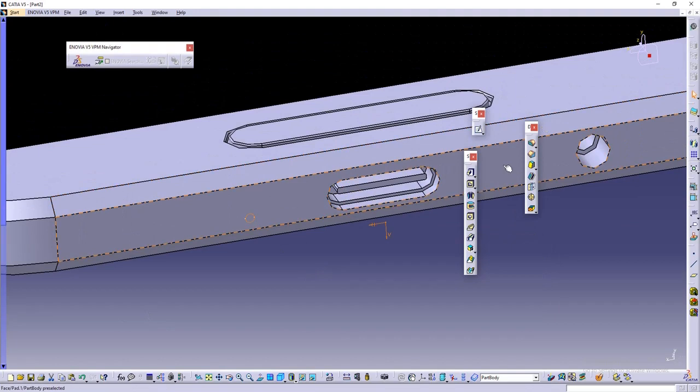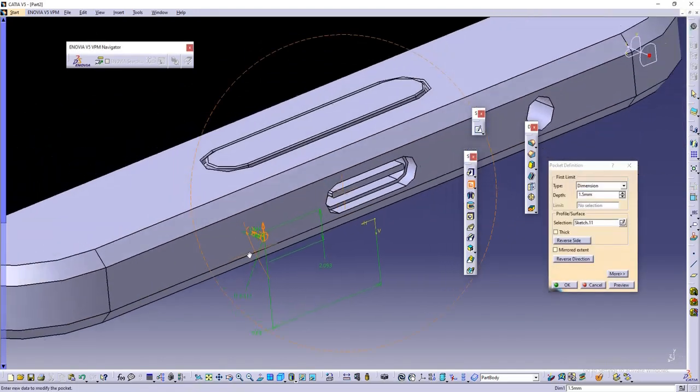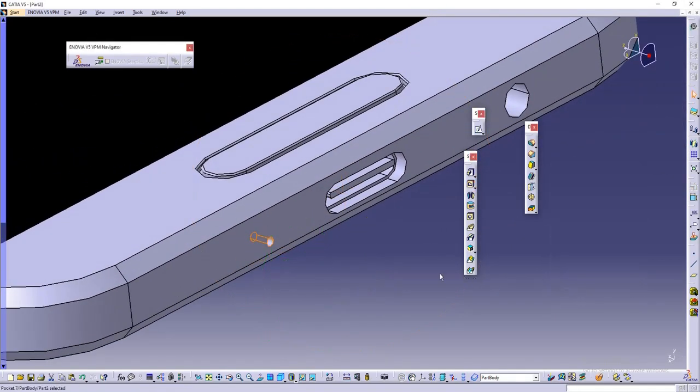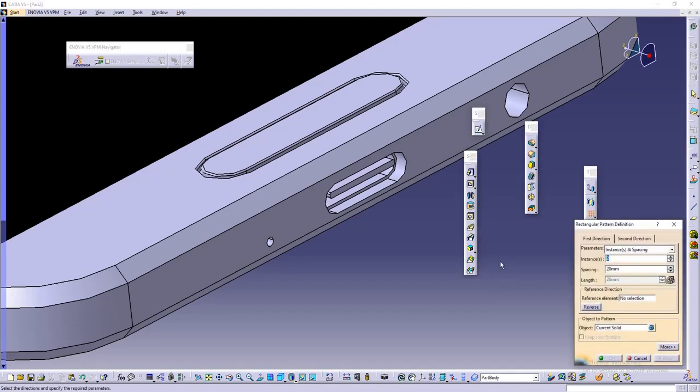Right. Go back, create a pad with certain, now it created the hole. So now again one more option is here, like I can just bring it out. The pattern option, rectangular pattern option. So here I can click on the rectangular pattern option, and now I have to select the portion or a thing which I want to multiply.